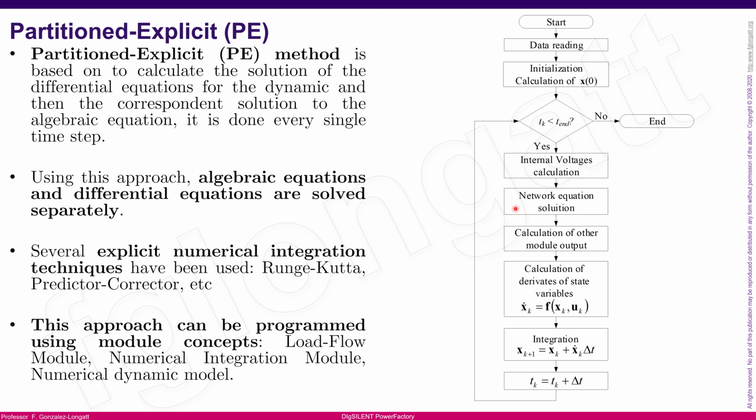Typically, every single power system analysis software has very strong routines for explicit numerical integration, like Runge-Kutta, predictor-correctors, and so on. In many of the commercial software available in the market, the full details of the explicit numerical integration are an industrial secret, and it's something similar for the implementation of the algebraic solutions, okay?